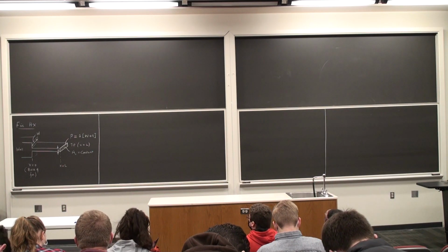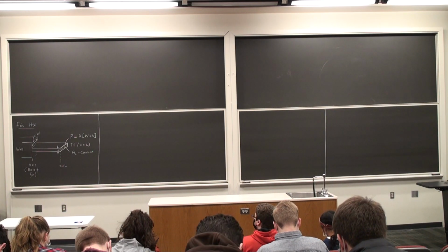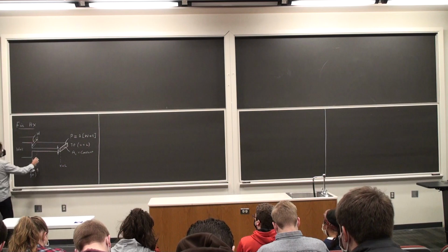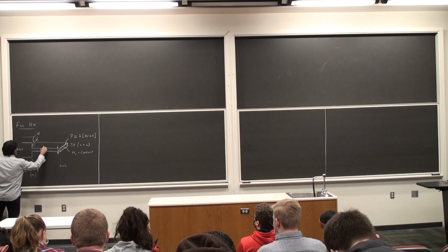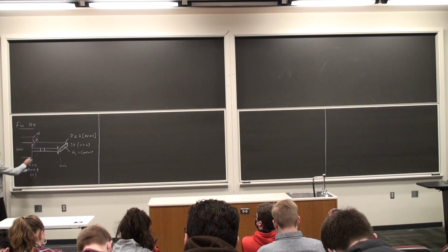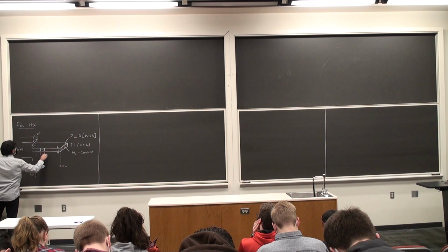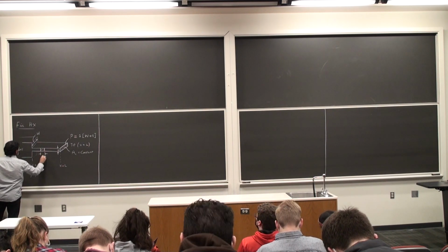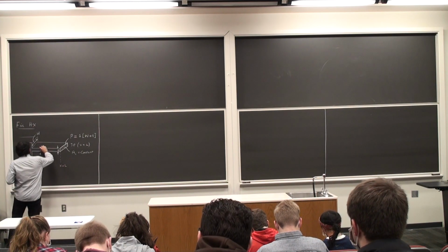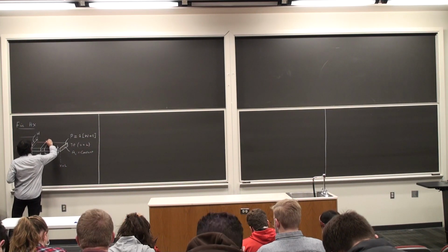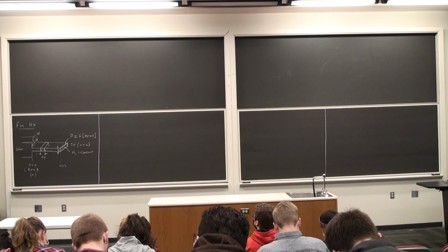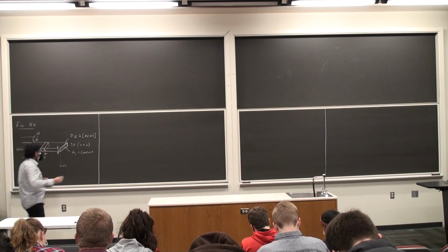And what we started doing last time was drawing a control volume. Then you take that infinitesimal control volume, look at the energy balance there, write the first law for that. So here is the situation. I'm considering a small element of length delta x along the x-axis. So here is that element, delta x, and then I'm drawing the control volume by removing that out. I'm going to take that piece out and draw it as a control volume right in the next board.